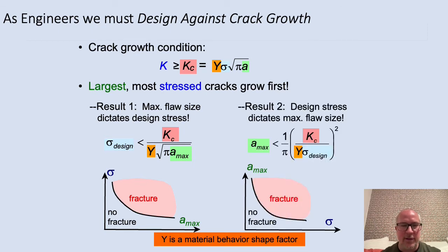And then we look at the design stresses, and that can also go back and relate to the maximum flaw size. So you can use both of these, and with step loading, you're able to get quantitative numbers that can be used in these calculations to ensure that the design stresses and the flaw sizes are used appropriately so that you can accurately do your design and engineering in a way that you operate in the location where no fracture is expected to occur.